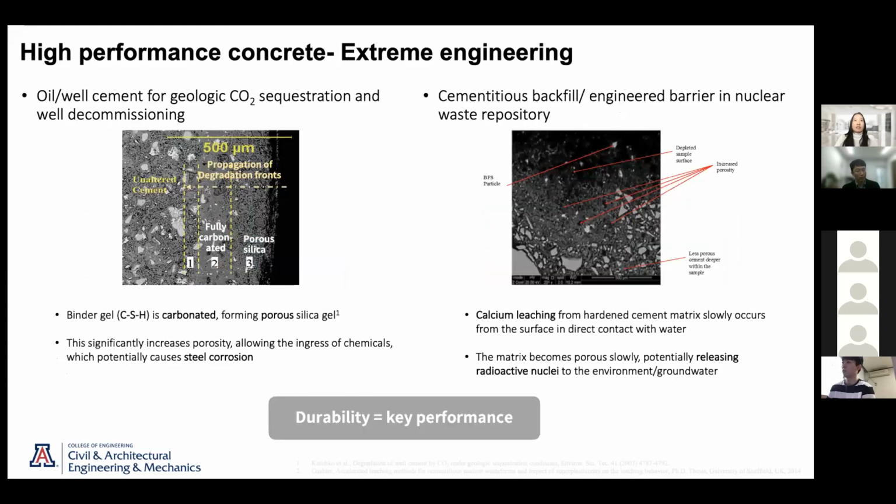However, limitations exist. For well cement usages, the carbonation leads to CSH scale dissolution, forming a porous structure and allowing the ingress of chemicals, which potentially cause steel corrosion. And for radioactive nuclei fixation, calcium leaching causes a porous structure, and it causes leaching of radioactive materials to the groundwater. Thus, durability is the essential and key performance for extreme environments.